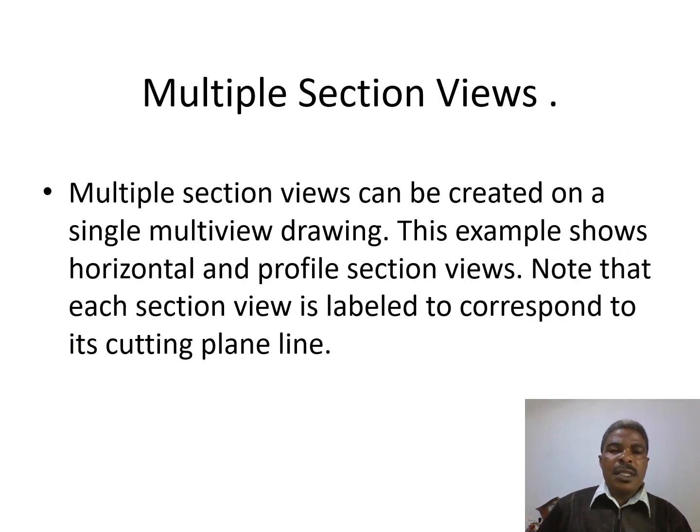So let's see what is called multiple section views. It happens sometimes we have two views or more sections in one object. So multiple section views can be created on a single multi-view drawing. This example shows horizontal and profile section views.